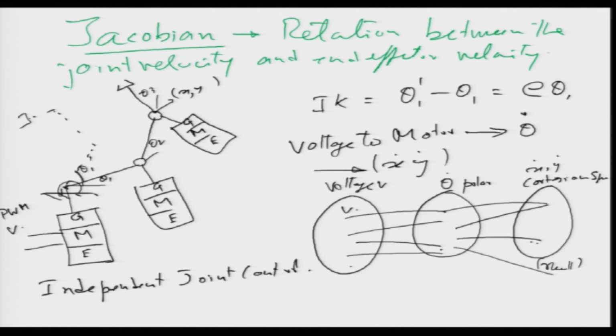Why is this important? Because it gives an indirect measure of the energy also. If there are places where the robot cannot go, that means there is no mapping between them. If there is no mapping, then the robot cannot go there, and that is called a singularity. So singularities are places where the end effector cannot go, because there is no relationship in this mapping. Sometimes you can give a joint velocity, but there will be no end effector velocity. So where did that velocity or energy go? That went into the null space. That went nowhere.